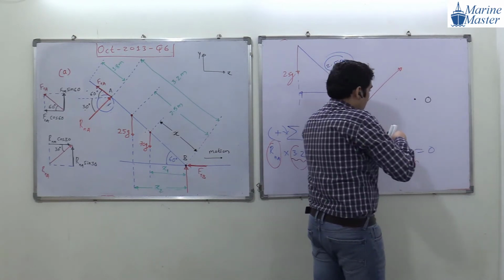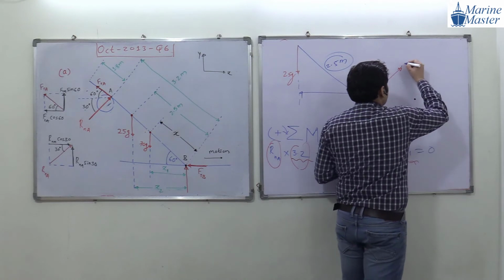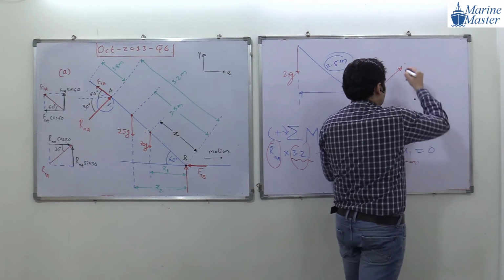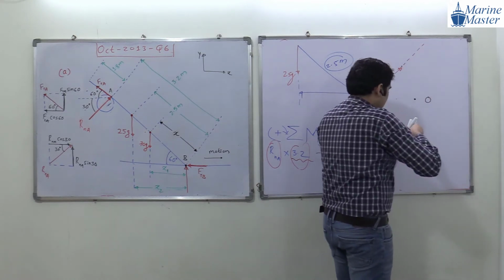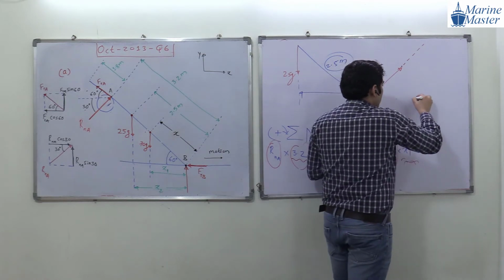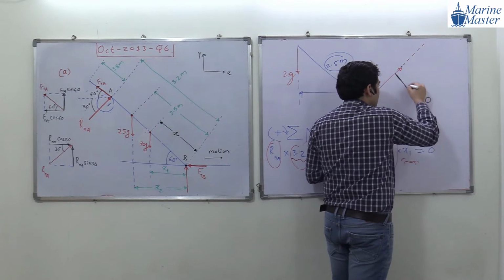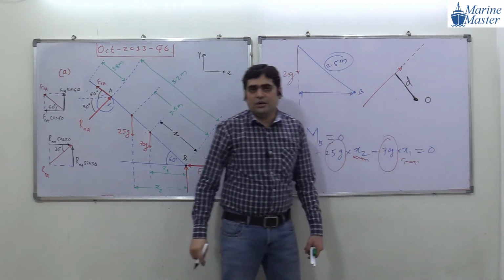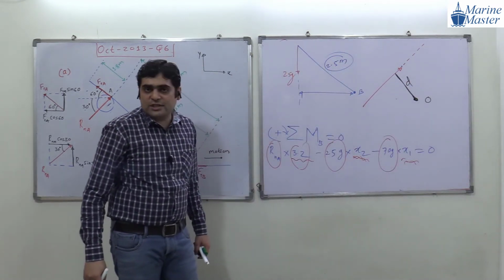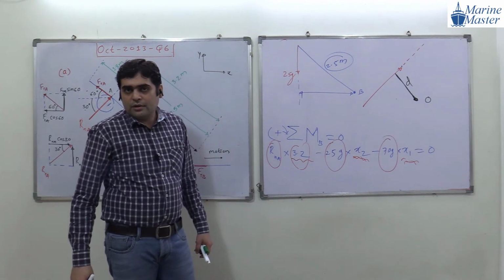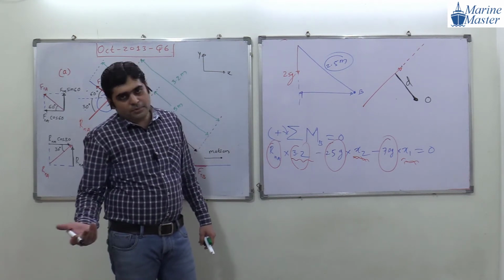This is what a force. How to get a perpendicular distance, guys? So, this is the line of action of the force. How to get a perpendicular distance from point O? We are going to draw one perpendicular line. So, this distance will be what, guys? Our perpendicular distance D. Are you getting my point? Try to see the scenario here. Force into perpendicular distance.